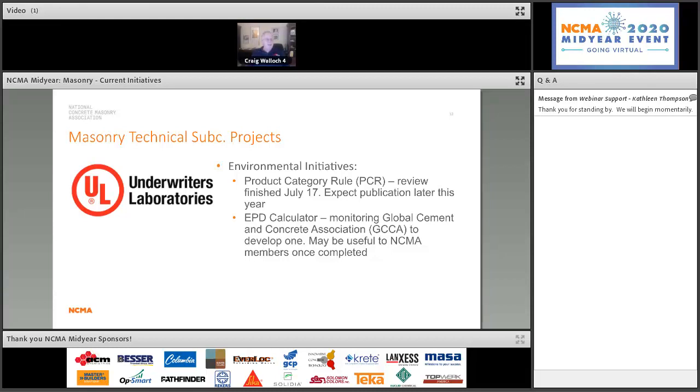So with the EPD, if people know how all this works, right? We're more familiar with the EPD, the Environmental Product Declaration. It's sort of like your nutrition statement of how we affect the environment. So that all of the EPDs are done consistently, first thing you need is a product category rules. So the product category rules basically set the groundwork for what needs to be in the EPD and how you do it. The PCRs are renewed every 5 years.